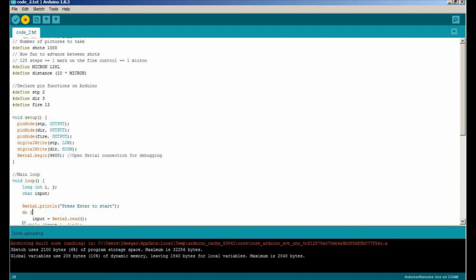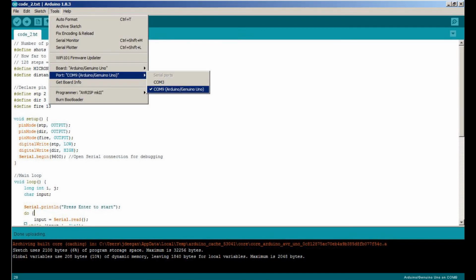The first thing that we need to do is to install the Arduino IDE on the computer that is driving the Arduino, and I will assume that you have done that. Here is the user interface with our code already loaded and saved. Next, we check the menus to see that the Arduino has been detected. We select it if it hasn't.